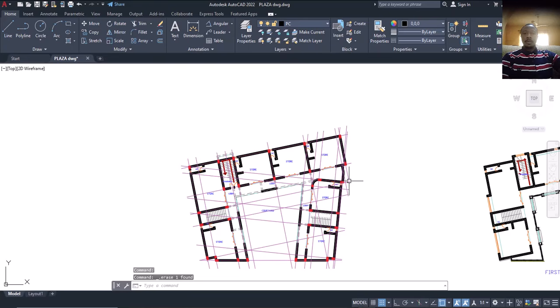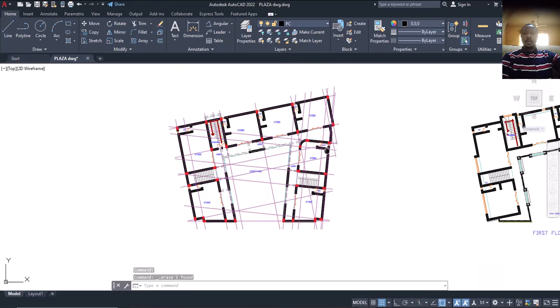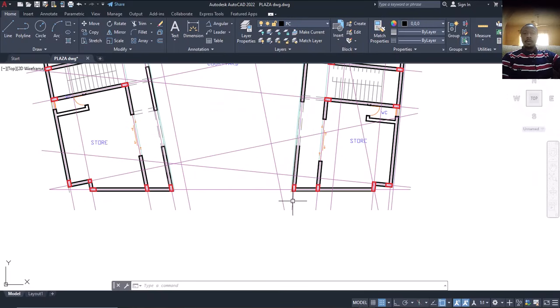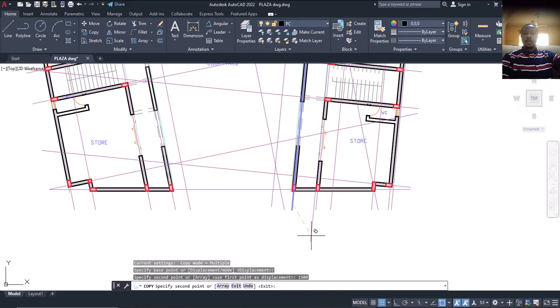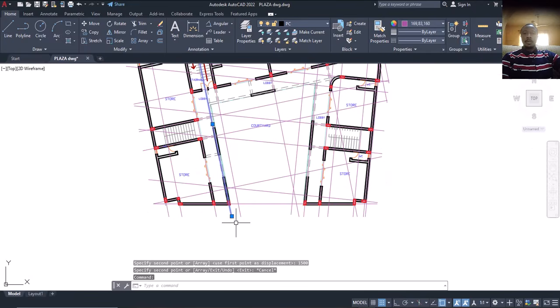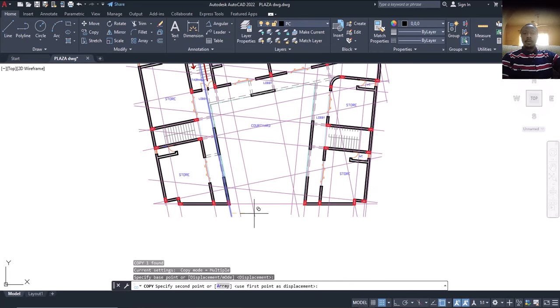The next thing is to trim off this particular place. So what I'll do now, press this one, then CP, I'm working inside now, so it's going to be 1500, enter. Then also come to this place again, CP, enter, from this point here I'm taking it out by 1500, enter.